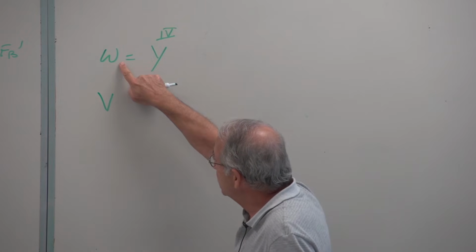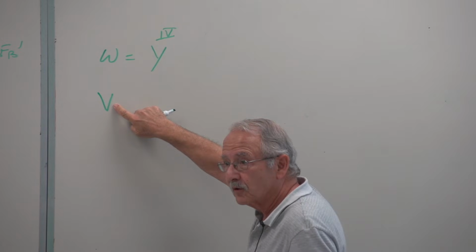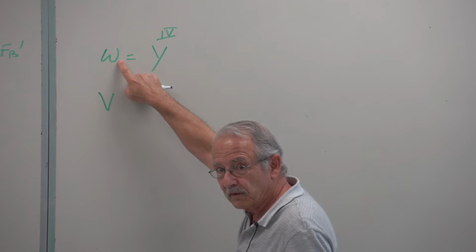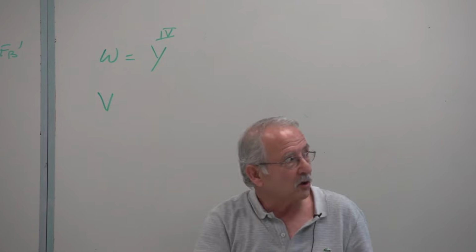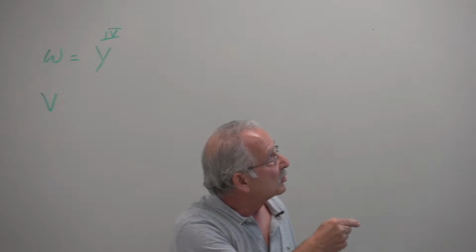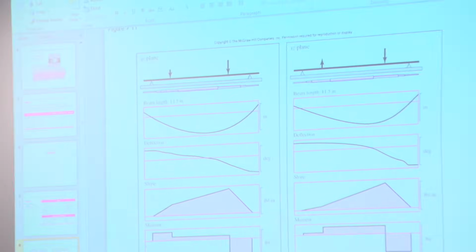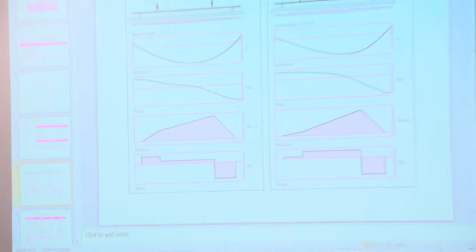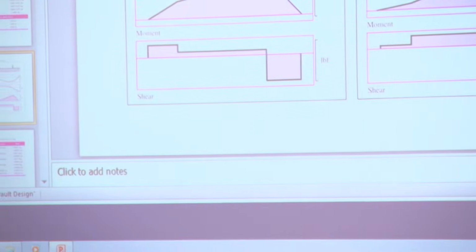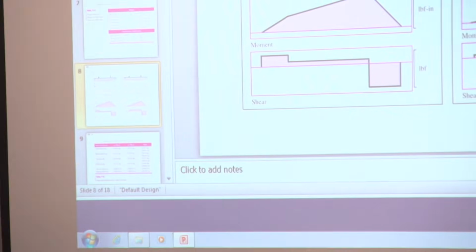Therefore, this is the derivative of that. So the magnitude of that is the slope of this. Take a look. There is no distributed load here. Therefore, the slope of the shear diagram is 0. No distributed load. W is 0. Not point load, distributed load.